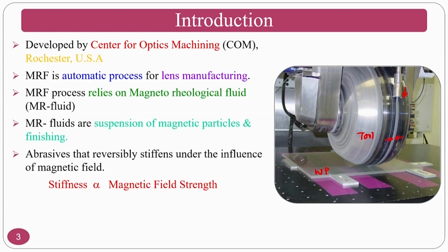What you have studied in the grinding wheel, this is also a grinding wheel, but it has a flexible fluid. Okay. In your grinding process, the bonding is fixed. Okay. Here what is happening is that in a particular cycle, the bonding between the fluid as well as the abrasive particle is fixed, but once it goes to the sucking tank, it will reshuffle the abrasive particles.